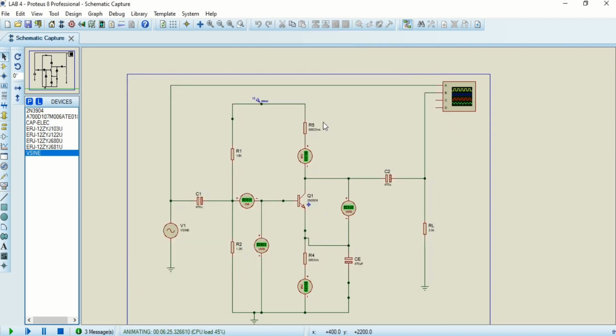In the oscilloscope, increase the input signal amplitude, which is Vs, until clipping is observed, and then reduce the input until the maximum output voltage that contains no clipping is found, and record the peak-to-peak value of both the input and output voltage. So that means we want to change the amplitude for the Vs.